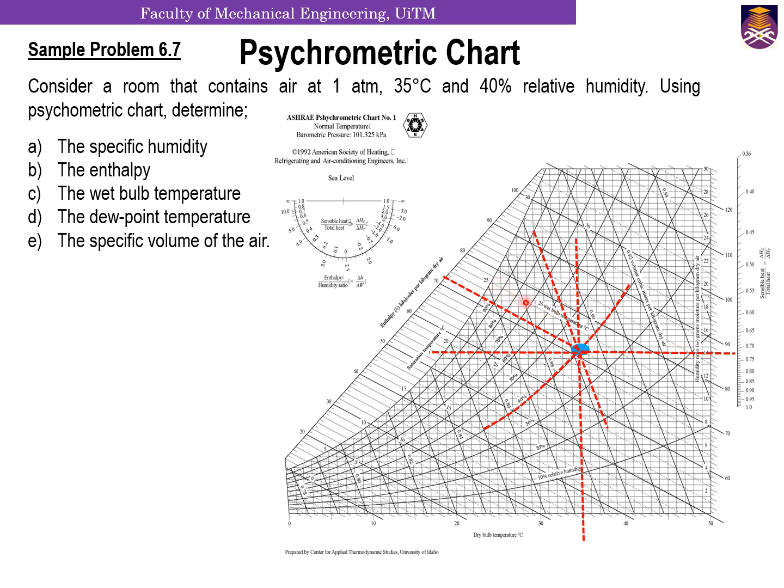You see that this is your wet bulb temperature that you have here, which is 25, and here is 20, and then there is an increment of 1. So this line here is on the wet bulb temperature of this line. So you will see that your wet bulb temperature is 24 degrees Celsius. So with that, you are able to find all the 5 parameters that you need to solve the problems for problem 6.7. Right? So hope the illustration helps you.